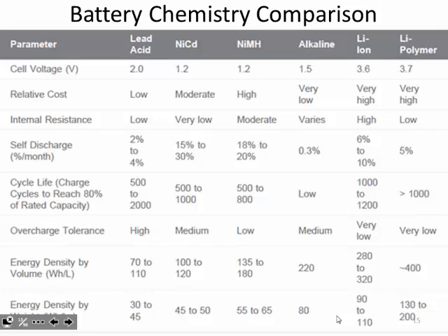Different types of batteries can only allow current to be drawn out at a certain rate, all right? Because essentially that tells you that there's an internal resistance in the batteries. So if you want a whole bunch of current really quick, some of these batteries can't provide it because they can only push out current so fast. Essentially there's something resisting the flow of current inside the battery. You can model it like that. Lead acid batteries and NiCad batteries had very, very low internal resistances.